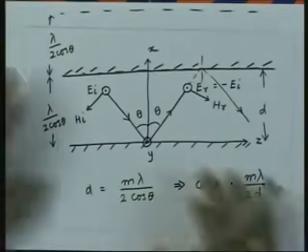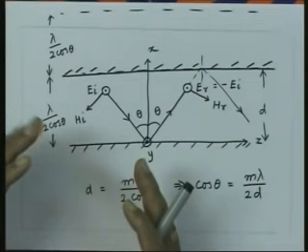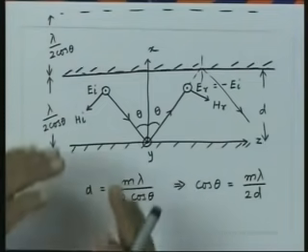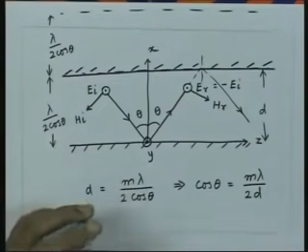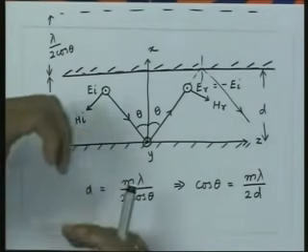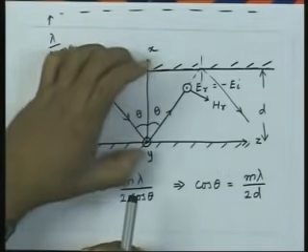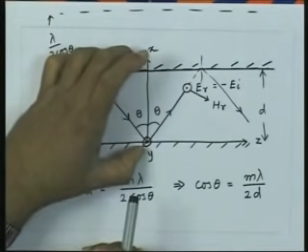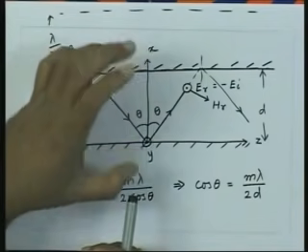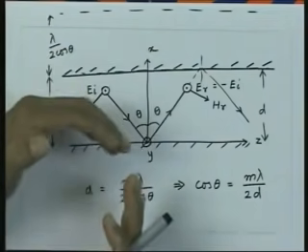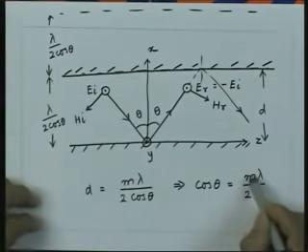This behavior of the bound structure is captured by what is called the modal propagation. So, what we are saying is, there is the wave which can be launched at discrete angles, superposition of these incident and reflected waves, they are going to create certain electric and magnetic field patterns in this, and you will have a unique pattern created for electric and magnetic field for a given value of m.